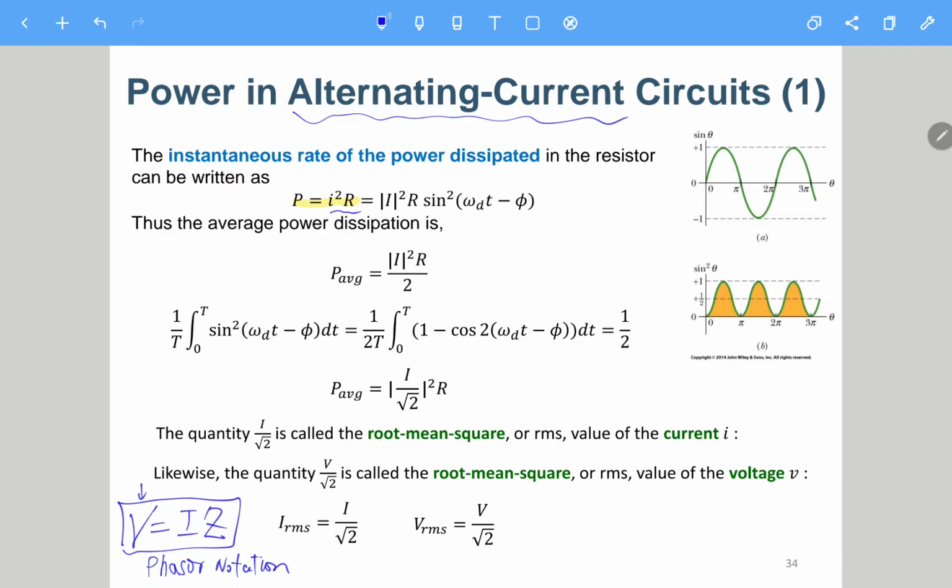It just oscillates from the inductor to the capacitor, and from the capacitor back to the inductor, back and forth. The power there isn't really consumed by the inductor or capacitor. It's just temporarily stored there. So the only element that can dissipate the power is the resistor.